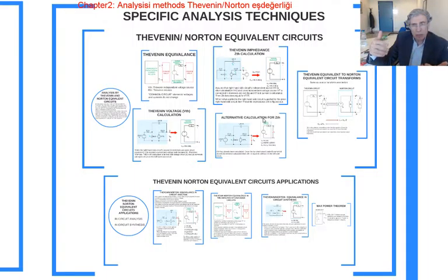So you've got to calculate all these resistors' powers. That means you've got to find all these resistors' currents and voltages and then make the decision about the limits required in order to use that resistor within the circuit. When you are buying a resistor, if your calculation result is more than 0.25 watts, you're not going to use that resistor.